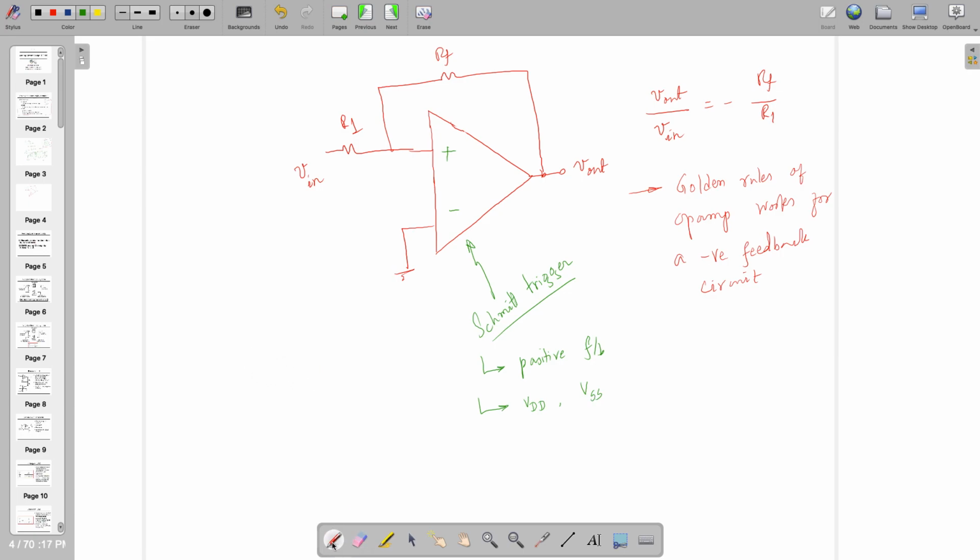And on top of that, if you look at the input output characteristic, this follows such kind of characteristic. Look at this, and this creates a hysteresis, by the way. The path which is taken from here may not be the same as the previous one, or it will have such kind of path. We need to find out whether it's coming from VDD to VSS or the other way around, and through that you can find out these points when it's actually changing the state from VSS to VDD or VDD to VSS.